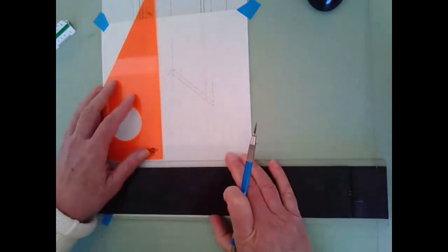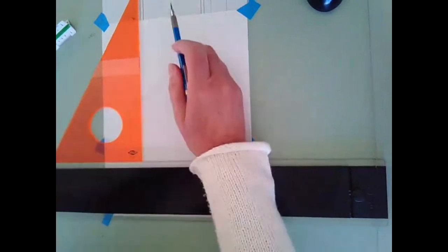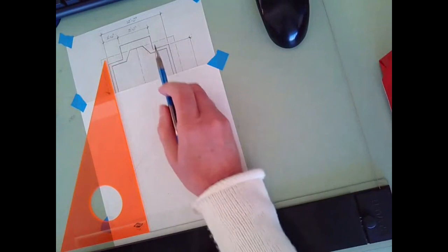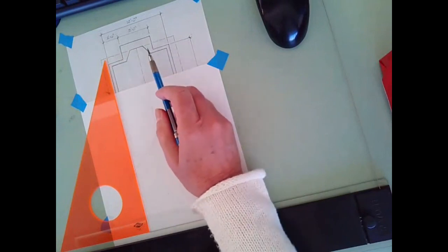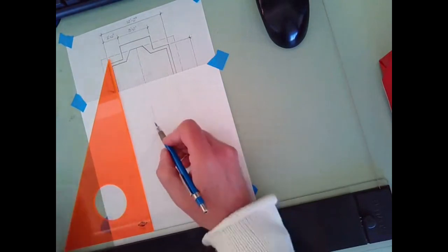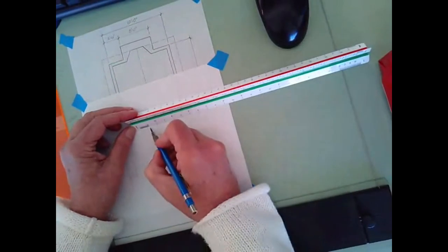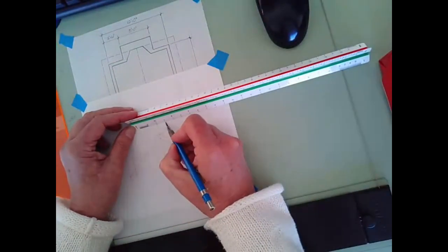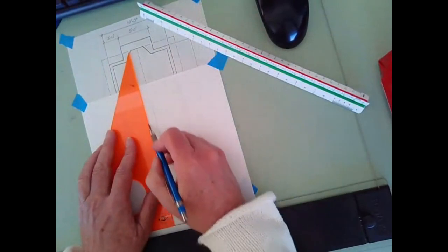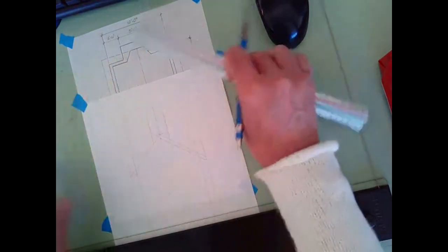The next thing I'm going to do is the chimney. Now, what we're seeing on the floor plan up here, I'll scroll up, is the chimney as you see in the plan. This chimney actually gets smaller, as most of them do, as you go up. It tapers up. So I said it was 2 feet wide, so it's going to be 1 foot each side of the center line of the roof. And then it's going to be 2 feet high from the highest point on the roof.